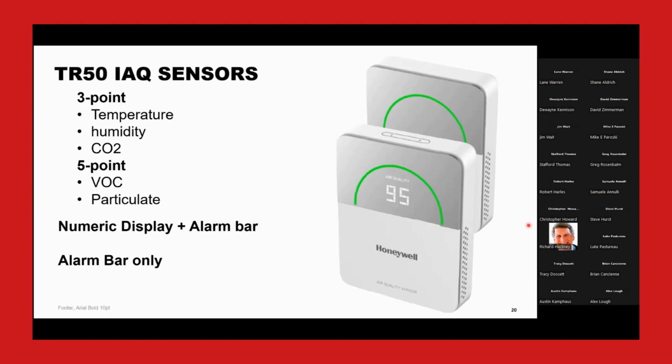Got it. Yeah, from the JACE's perspective, it's BACnet over IP. It doesn't know what T1L is. Again, T1L is an electrical thing. It's not a protocol thing. You're coming out of the JACE or the Cipher or the LAN, the network switch or router with a piece of RJ45, and instead of plugging RJ45 into the controller, you plug RJ45 into the adapter and run twisted pair out. But the protocol hasn't changed. It's BACnet over IP, hopefully BACnet IP secure after that.